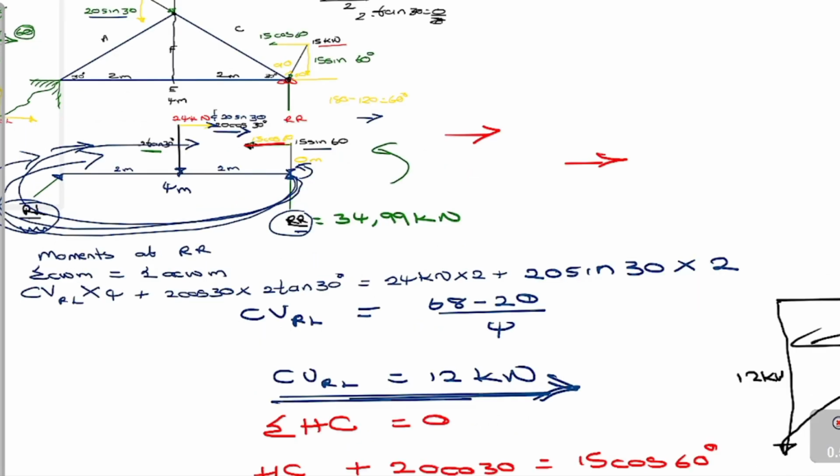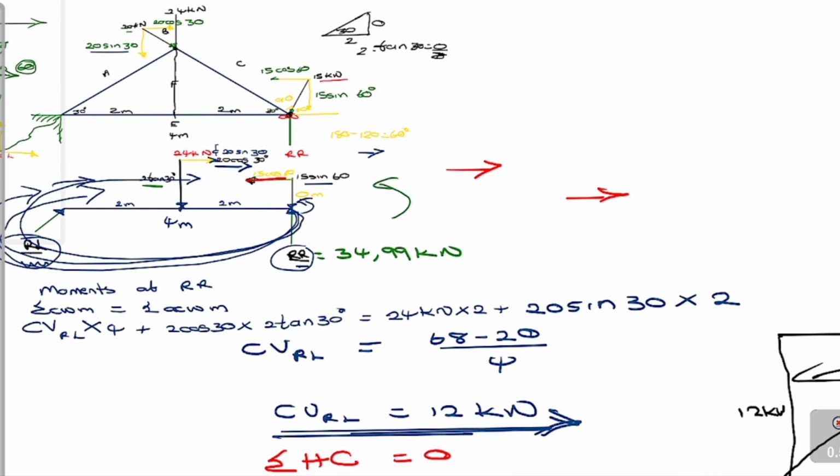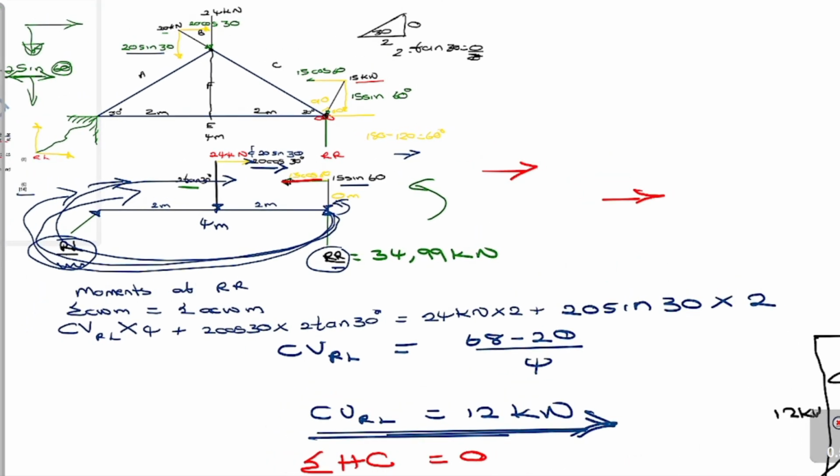Right, so let's just go over this before I say my goodbyes. So guys, this is just this question. What you had to do first was transfer whatever you were seeing in the diagram onto your load diagram. You had to separate the vertical and the horizontal components. And then you also need to know how to find your reactions, as in the direction, using the anti-clockwise and clockwise direction method.